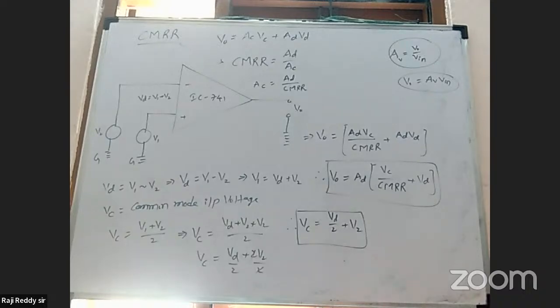Analogous signals are converted into ramp or square shapes and other things. This is used in the practical operational amplifier. With the help of the slew rate, we are changing the wave formation. Sine wave to ramp, ramp to square, square to some other different wave formation. For the waveform changing purpose, we use the slew rate.